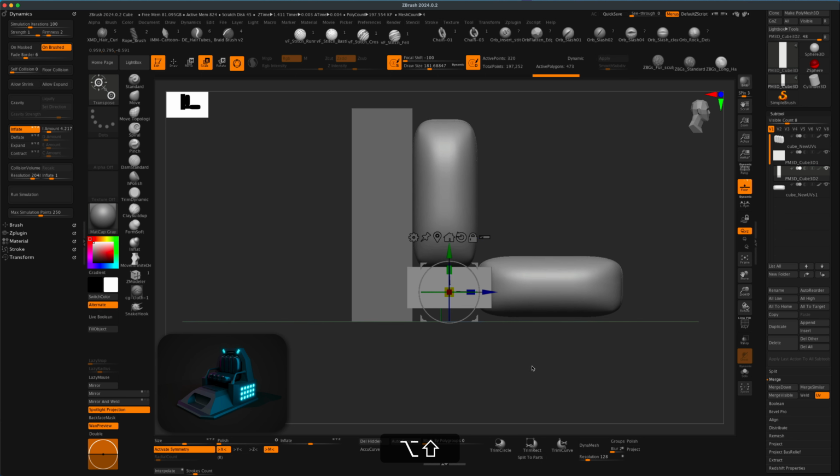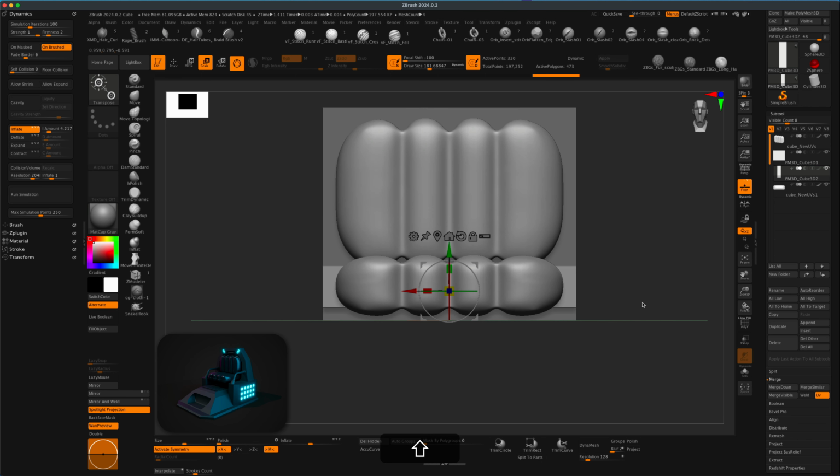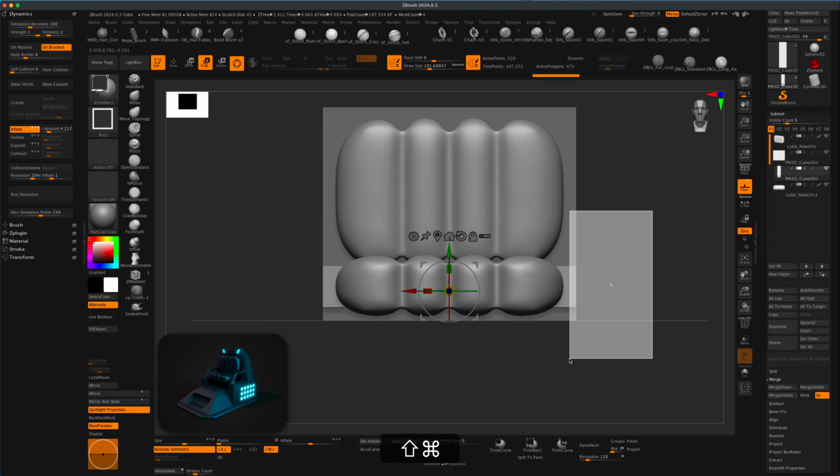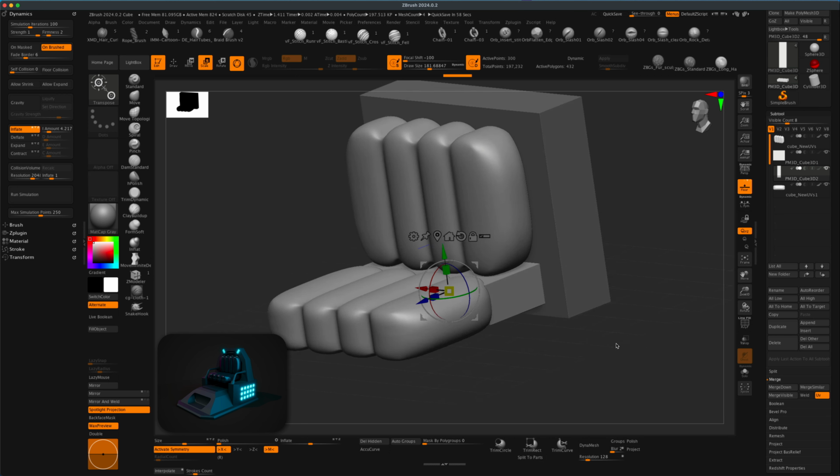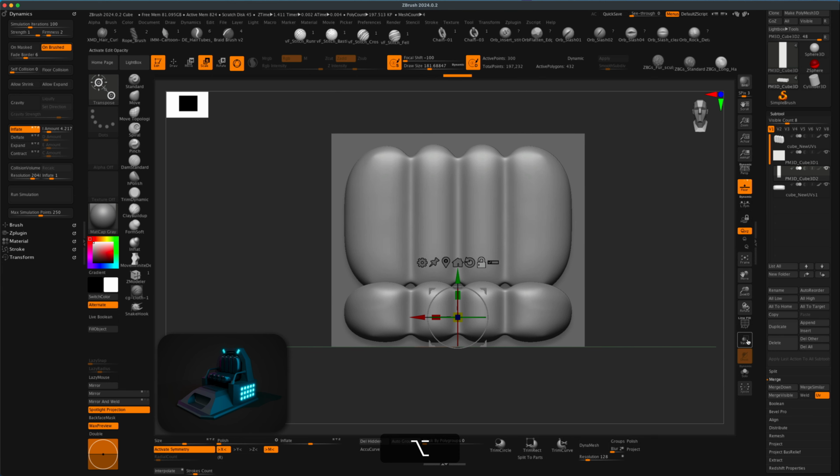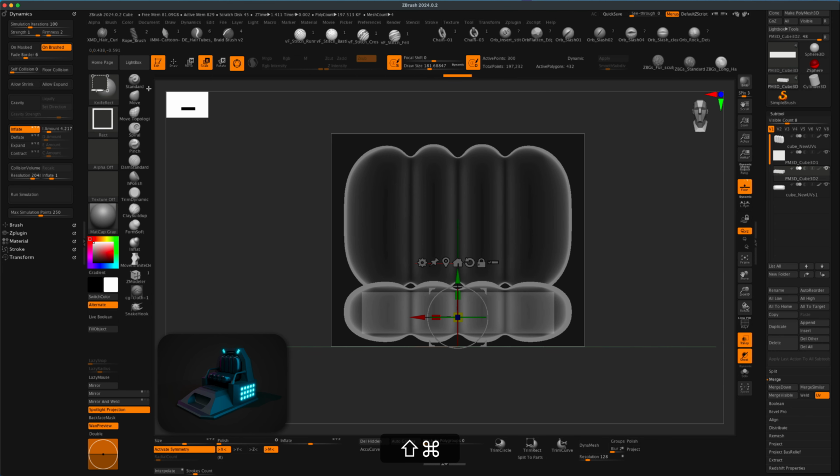Now, another thing I could do is, let's go to this view, let's do Control Shift, and let's maybe trim this a little more, maybe even something like that. All right, that's cool. We can also turn on transparency mode. Let's do Control Shift, and let's maybe switch to a knife. And why not also trim? Let's create a little bevel here. The way I'm doing this is I'm holding down the space bar to move this around, right? And then if you remove the space bar